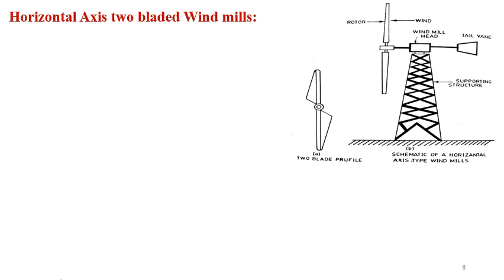The rotor blades are continuously flexed by unsteady aerodynamic, gravitational, and inertia loads when the machine is in operation. If the blades are made of steel, flexing reduces their fatigue life. The tower is also subjected to loads like gravitational, aerodynamic, and inertia loads.